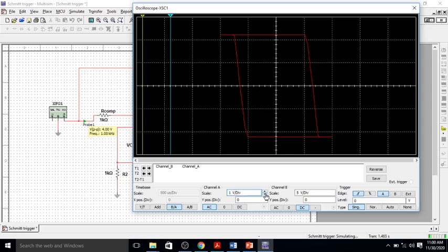And using this also, you can easily calculate almost 1.2 volt is UTP, minus 1.2 volt is LTP, and V saturation is this vertical division 2.1 multiplied by 5, same minus V saturation is 2.2 multiplied by 5. So this is how you can calculate the plus V saturation, minus V saturation, UTP and LTP.